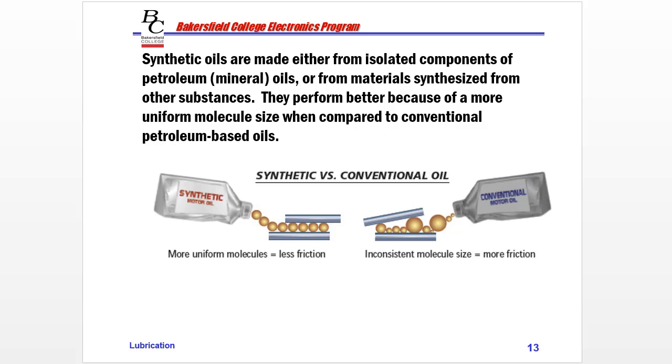So for the most part, synthetic versus conventional is about the same cost, because with conventional it's cheaper, sure, but we have to replace the oil sooner on a more periodic basis. Where synthetic will last longer, a lot of times over twice as long. So depending on that and the price of the synthetic versus the conventional, you may save a little money with synthetic. But it's more expensive, you don't have to change it as much, so they're pretty close in cost.